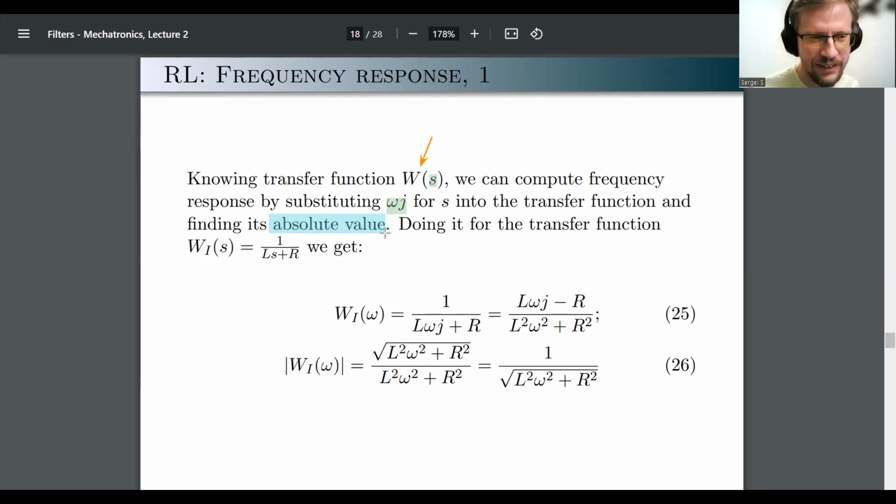This is just poetic stuff, not mathematics, but a simple explanation looks like this. Your Laplace variable, you can think of it as representing a solution, like an eigenvalue, to an ordinary differential equation, or a second order ordinary differential equation. And as long as you're interested in frequencies, what you need to care about is the imaginary part. So you can set your real part to 0 and just look at the imaginary part. That's kind of what we're doing.